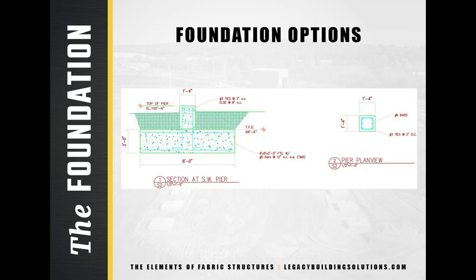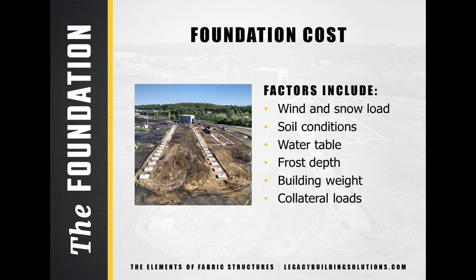With the lighter mass of fabric, several foundation options are available, ranging from traditional cast-in-place concrete to less invasive earth anchors or helicals. Partnering with the manufacturer from the earliest phases of pre-construction may make it possible to reuse all or part of an existing concrete foundation, another way to save time and money during the construction process.